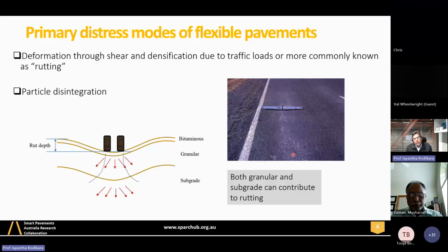That's a very good question. Of course, we have to look at the traditional triaxial test where a 1:2 ratio is used. The reason we use it in triaxial is we get a uniform stress condition in the middle region, which we can use for analysis, because we are trying to eventually get an element of soil and then develop a constitutive relationship. So stresses must be uniform. Even in the triaxial test, edge conditions can distort the stresses, but that's why that longer length is used.